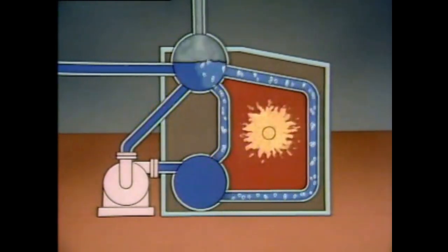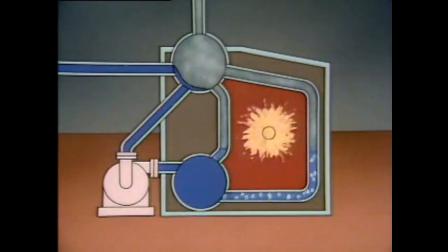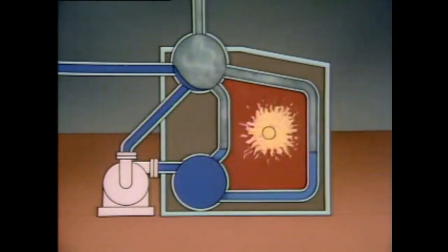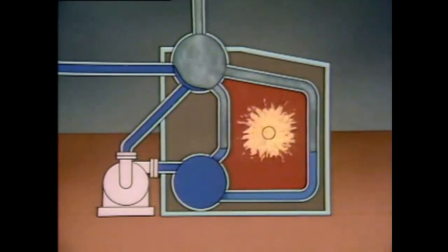Hypothetically, though, if the pump stops, the water will no longer circulate properly, and the boiler could boil dry and become damaged. To make sure there is proper water flow, most controlled circulation boilers use 2 or more pumps. So, even if one pump stops, the other pump will provide enough circulation to prevent damage to the tubes.